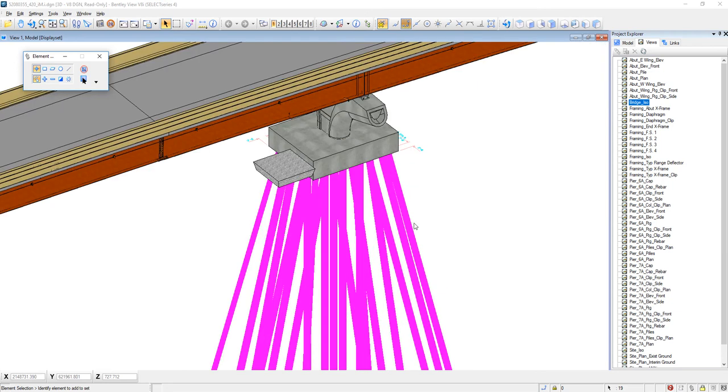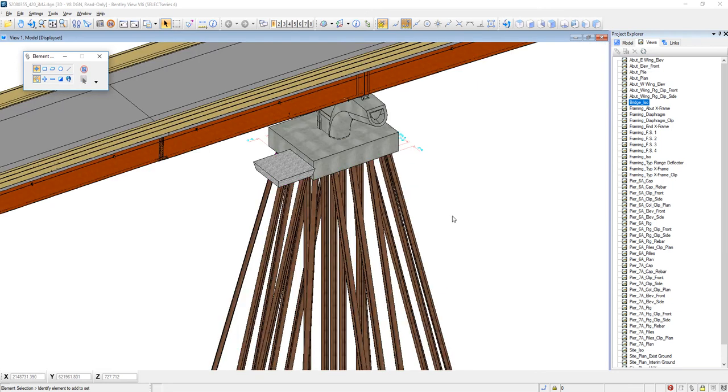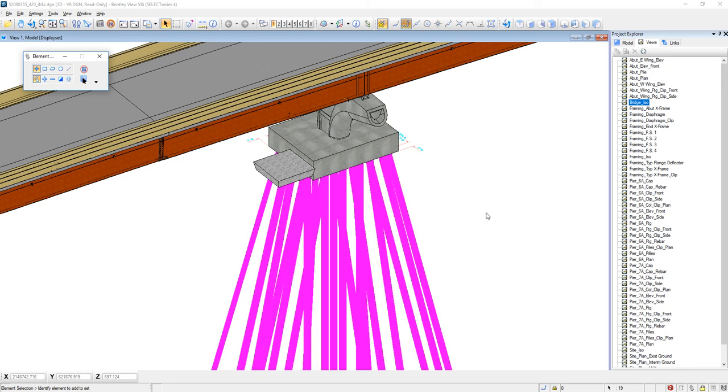So I was showing you as I click each element, it unselects the element I had selected previously. Now, in order to select multiple elements, holding down the control key is one option. If I have this one selected, I hold down control, I can also select other elements. I can also make that combination with the box. So let's go ahead and just left click that element, hold down control, and make a box with the rest of these elements. And you can see that was all added to my original selection.